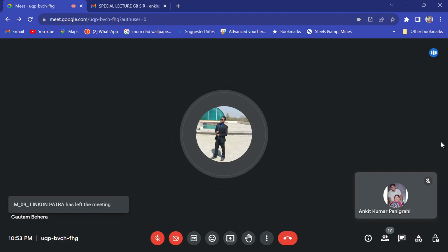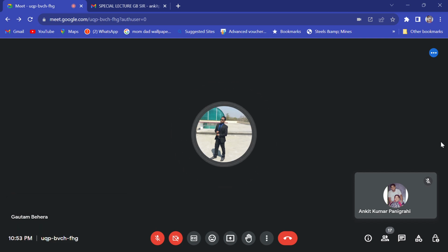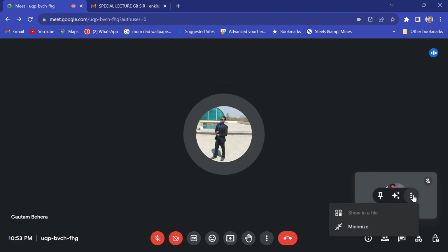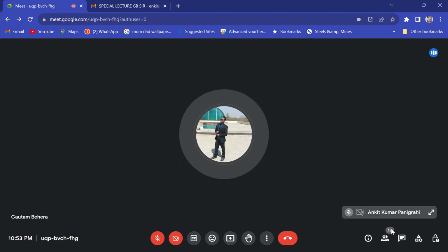Can you tell me how to remove the dissolved oxygen from the steel? By reacting this oxygen with carbon. Oxygen cannot be removed easily. It will form carbon monoxide by reacting with carbon, and this carbon monoxide has to be removed. If the carbon monoxide gets trapped in the steel during solidification, it will give rise to what? Blowholes. That is a problem.